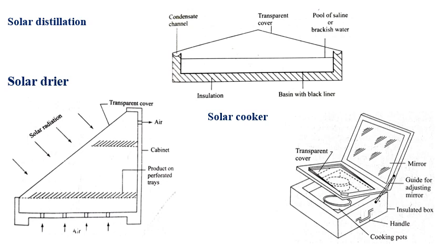Okay, so you can see in the diagram a flat plate box type design, which is the simplest of all the types of design. Maximum no load temperature with a single reflector reaches up to 160 degrees centigrade. In multi reflector types, four square or triangular or rectangular reflectors are mounted on the body.